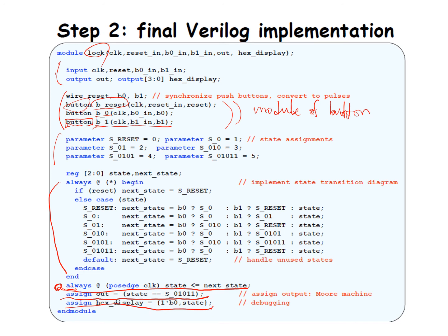Okay, this is final. I'm going to ask you one question. For this kind of implementation, we use the flip-flop shown here. For the reset, when the reset comes in, the combinational logic receives that reset signal and assigns the state to the reset state. Is this a synchronous reset or asynchronous reset? For synchronous reset, the reset happens on the next rising edge.